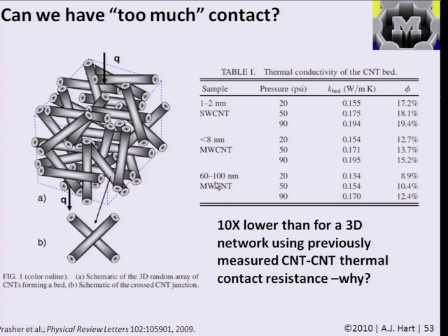And what they found here is that the fact that they were pressing the nanotubes in such tight contact, having many, many tubes in contact with many, many other tubes, means that they gave so many opportunities for phonon scattering that they significantly decreased the thermal conductivity of the net material. So they essentially took a case where if you pulled out any one of these nanotubes and suspended it across a gap, you would have a thermal conductivity of, say, 1,000 watts per meter Kelvin or higher. But if you take a huge number of them and you slam them together in a densely packed powder, the effect of scattering between the tubes, essentially deflection of those vibrations, renders the net conductivity lesser than a regular polymer would have.